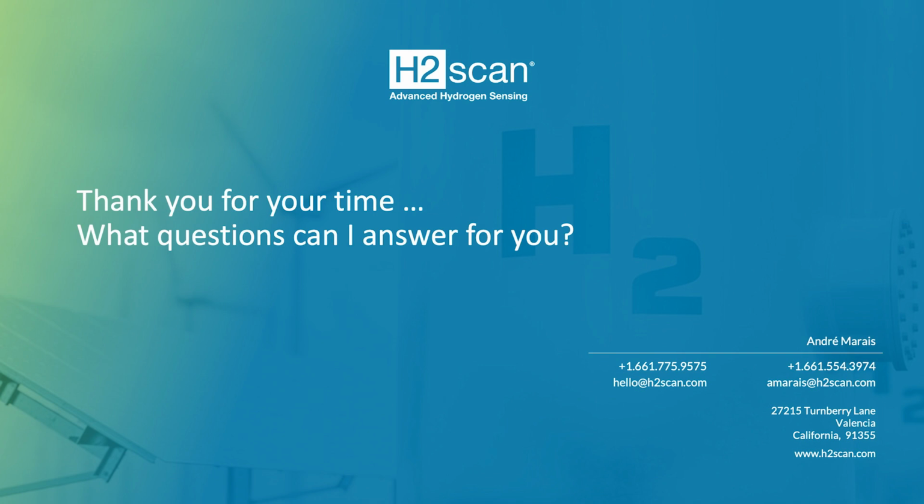Great. Michael asked a very interesting question. He'd be interested in seeing a comparison of H2 scan results with actual DGA. How often do we see false positives? We've never seen a false positive. One of the particular issues of our sensor that differentiates it is that our technology is not cross-sensitive. Our sensor only reacts to hydrogen.